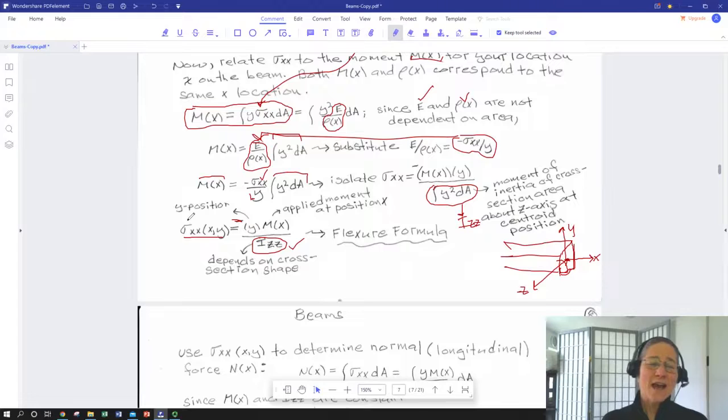So if you were to say, okay, I want to design a beam around the worst possible case, right? I've got to pick a material, or I've got to pick a cross-sectional shape that's big enough. I'm stuck with the material. I know what my maximum longitudinal stress is. I'm going to base it on some safety factor versus my yield stress, say. Something that I don't want to cross.